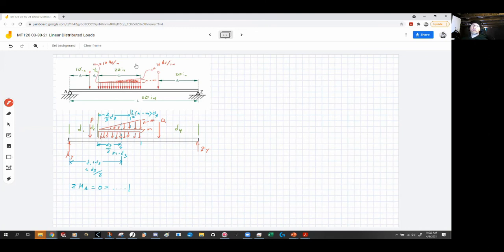Okay, and so this is going to be M times D3. So that's going to be 220 pounds times, now this total distance is D1, D2 plus D3 over 2. So that's 10 plus 4 plus 11 times 25 pounds.